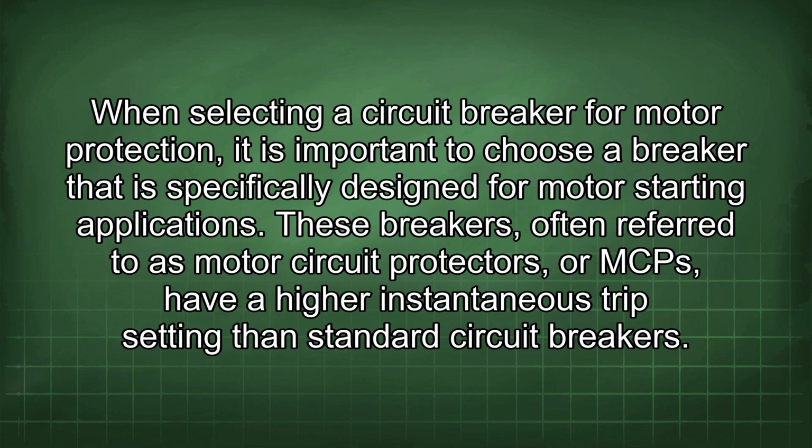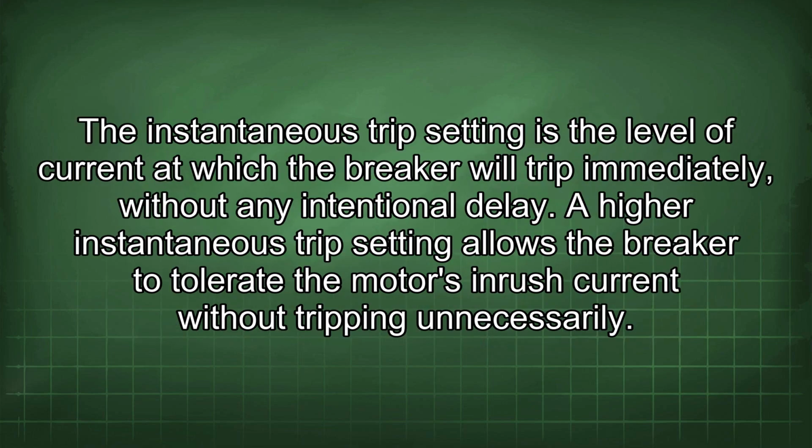motor starting applications. These breakers, often referred to as motor circuit protectors, or MCPs, have a higher instantaneous trip setting than standard circuit breakers. The instantaneous trip setting is the level of current at which the breaker will trip immediately, without any intentional delay. A higher instantaneous trip setting allows the breaker to tolerate the motor's inrush current without tripping